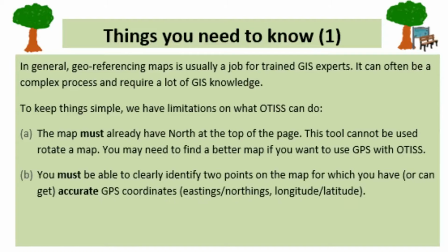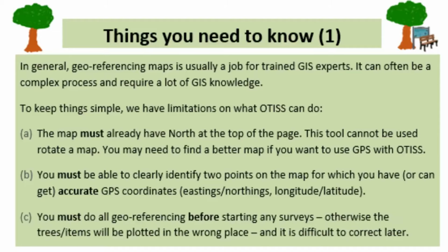You must be able to clearly identify 2 points on the map for which you have accurate GPS coordinates. And you must do all the georeferencing before you start surveying. Otherwise the trees will be plotted in the wrong place and it's difficult to correct later.